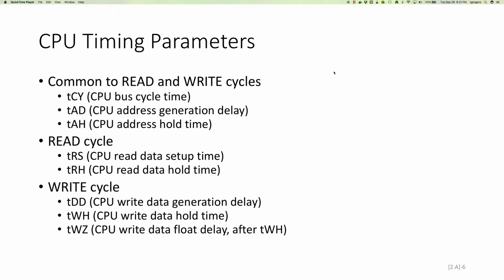Okay, so setup and hold times are fundamental to circuit operation. And if we're doing a read, which means that the CPU is going to be reading the data from the data bus, we need to make sure that we do not violate the CPU's setup and hold time parameters. So when we go through the example and piece all these things together, these setup and hold time parameters are the fundamental piece that we're trying to make sure is not violated, with all of this other timing parameter stuff.